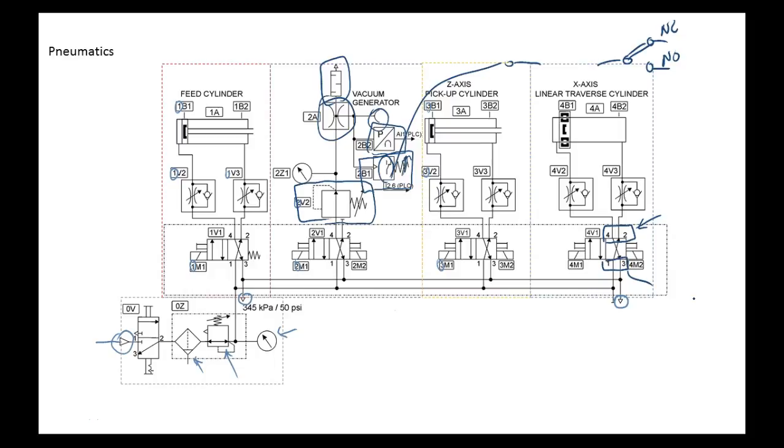So what we do is most of your valves that you buy now, they can come standalone, or they leave off the bottom and you can mount them on the manifold. When you mount them on the manifold, they share the pressure and they share the exhaust. So automatically, that's going to save a lot, right? You understand? It's going to cut down on the amount of maintenance, because now you're not dealing with 8 pressure hoses trying to figure out where they go.